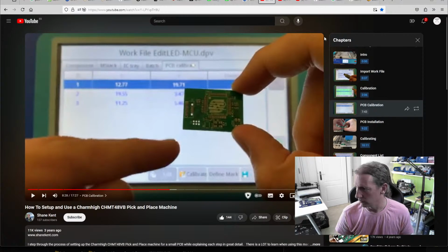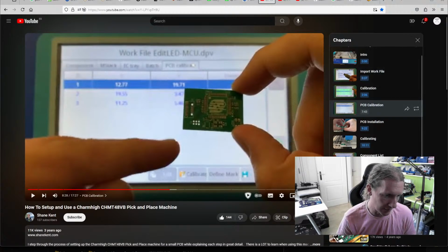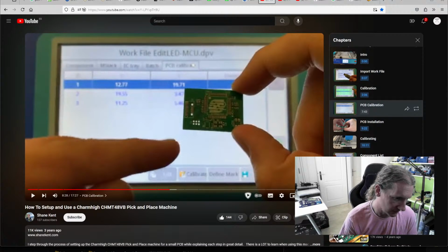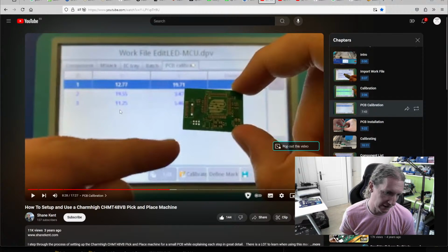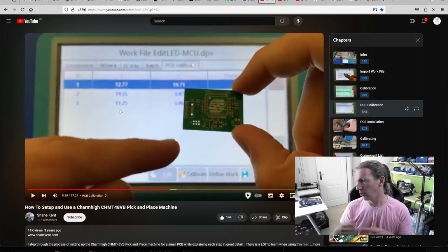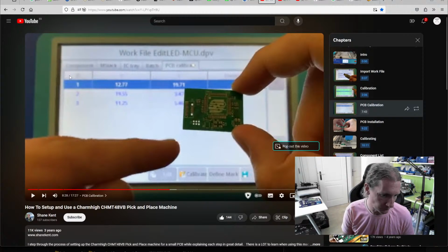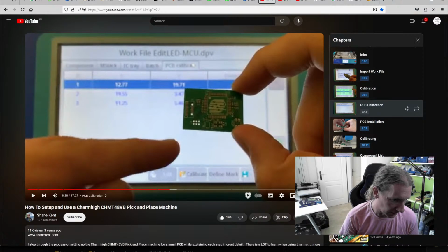So it has to support being able to make mid-job changes, and be able to fix issues as they occur. Common issues are failure to pick, blocked nozzles, and problems with vision, for instance maybe the sun came out and now it's affecting the cameras on the machine, and so on. Stuff like that. It happens.